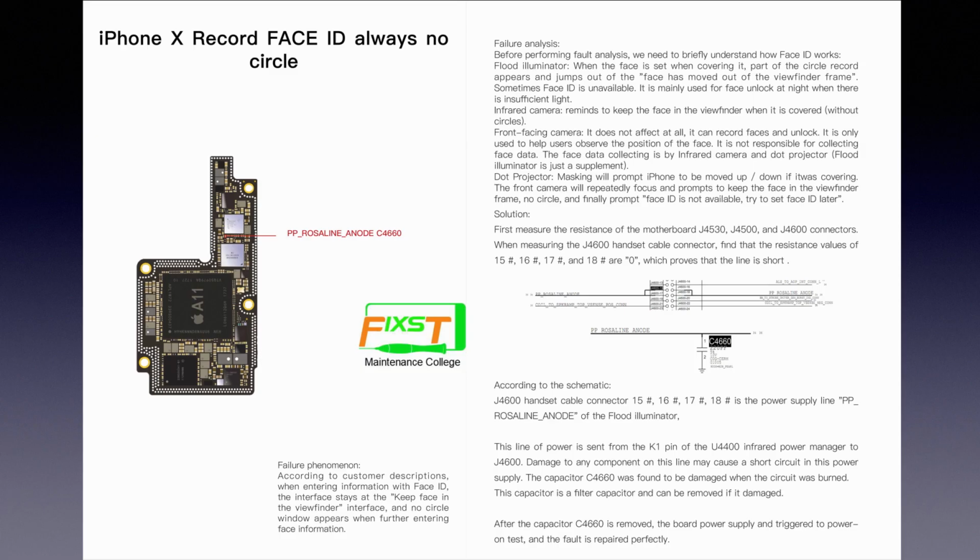After removing capacitor C4616, we install and test the phone again. This problem is finished. If you have enough time, you can take out your iPhone X, XS Max or another model, and cover one of the Face ID components with something to test it. You will know more about it. In this photo, we are just talking about it simply. You can also check it one more time.